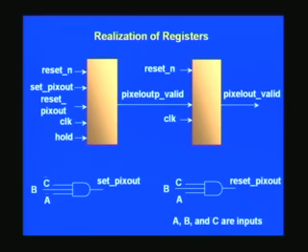So, naturally you have got to have some mechanism of delaying, and because the data is delayed, we have to still keep track, keep pace with it. We need to delay this pixel out valid, which happens one clock cycle prior to what we want. That is the reason why we have one more register here. So, this is actually to delay a register, and the output is pixel out valid, for which the codes are like this.